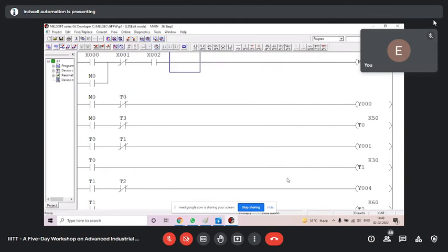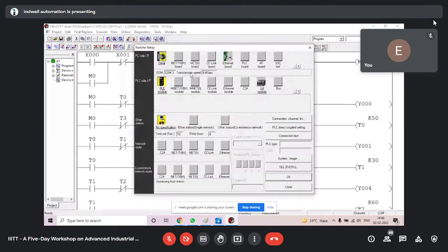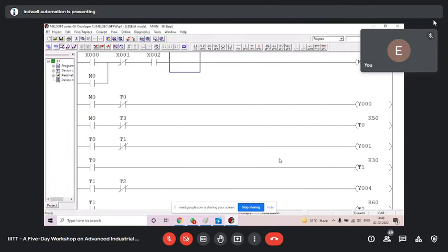One thing let me tell you. Again, you set this, check connection, it is successful. After that, if you don't click this OK, then it won't be communicated. So you have to click this OK. Don't skip this. I made this mistake, and it took a long time to communicate with my PLC. So that OK is very powerful. You have to click that.